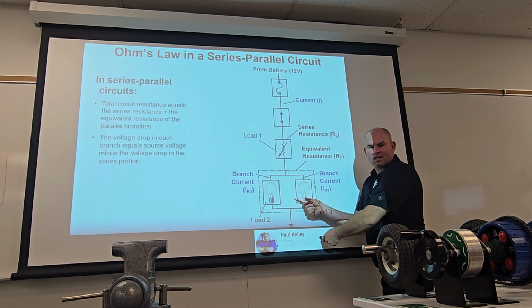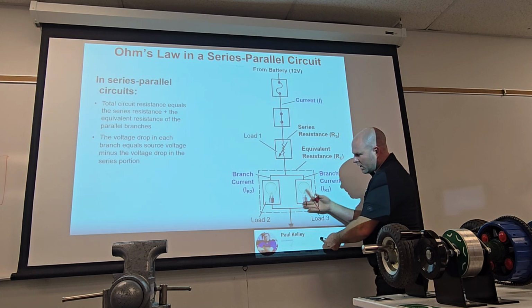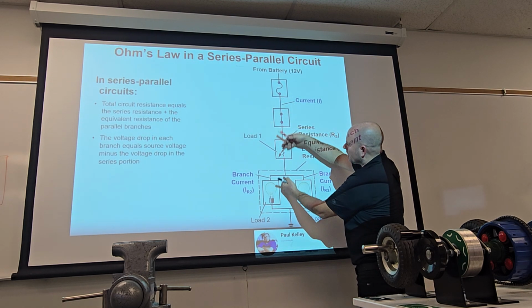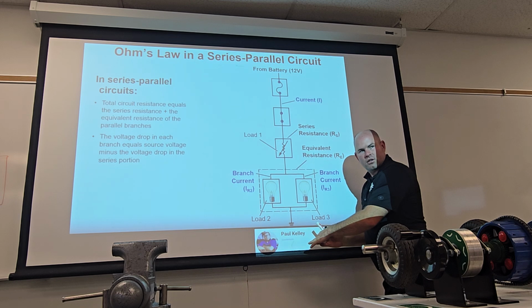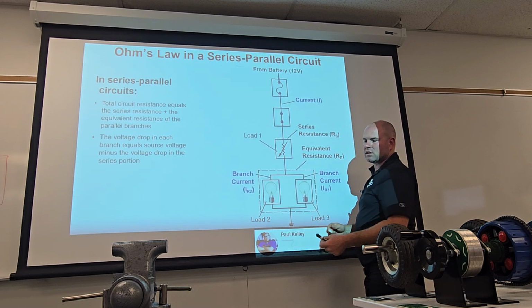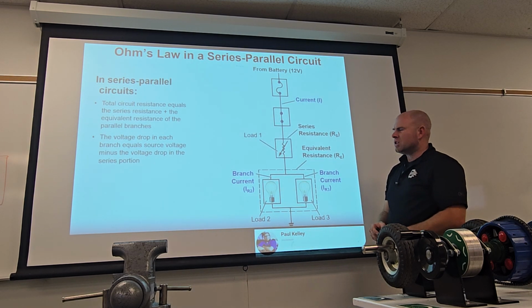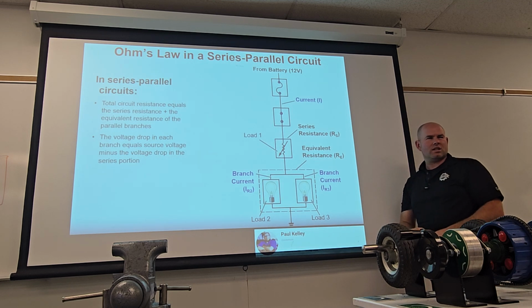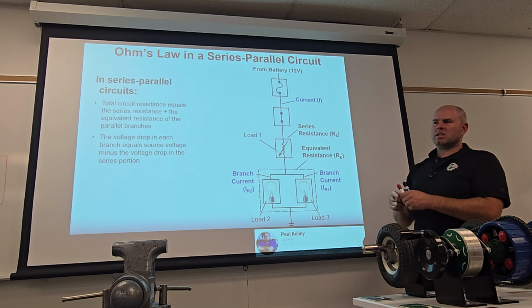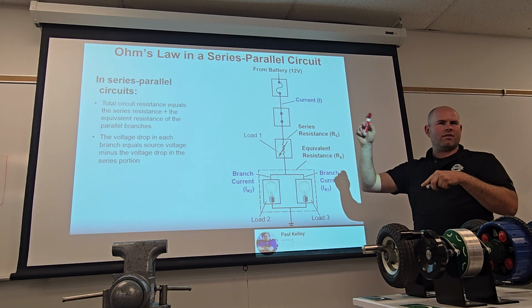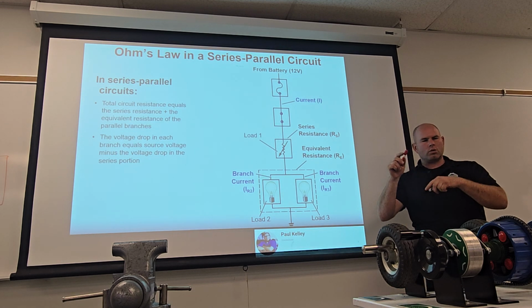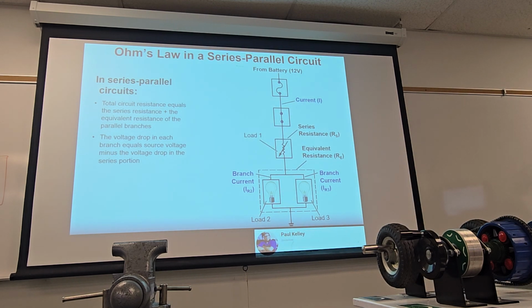But if it has 0.2 ohms, I know somewhere these wires are shorted to ground. Make sense? That's a test that we periodically have to do, especially with sensors. When a sensor's reading is messed up, a lot of times we're measuring to see if the sensor wires are shorted to 12 volts or shorted to ground or shorted to another wire. All electrical tests.